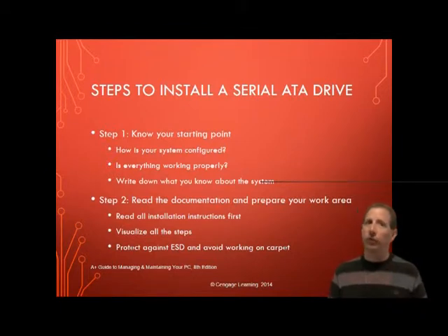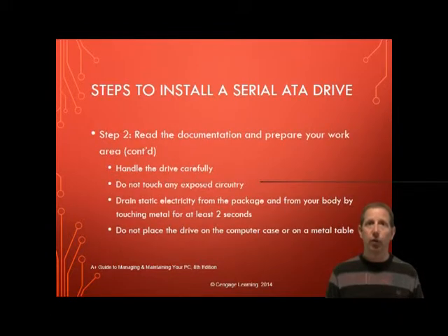Remember the basic rules concerning static electricity, which you learned in the earlier chapters. Be sure to protect against ESD by wearing a grounding bracelet during that installation. You need to also avoid working on carpet in the winter and when there's a lot of static electricity. Some added precautions for working with a hard drive are as follows. Handle the drive carefully. Do not touch any exposed circuitry or chips. Prevent other people from touching exposed microchips in the drive.